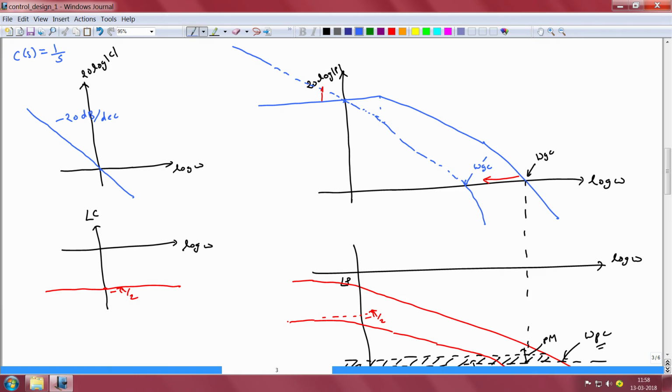So, this is the price that one pays for simply going with an integral controller. While we are able to achieve high gain in the low frequency region and thereby achieve very good performance in tracking references and rejecting disturbances and so on in that frequency range, the disadvantage is that we are reducing the closed loop bandwidth of our control system and therefore are not able to track references that we could track reasonably well earlier.